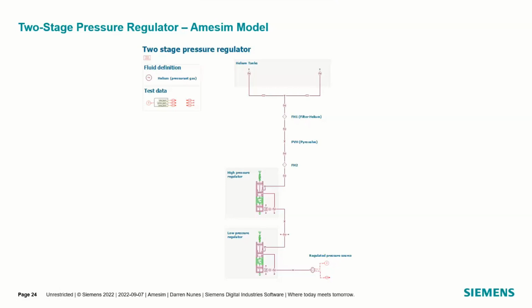The tanks are ideally insulated due to the lack of information. We really didn't look at heat exchange or materials involved. The two stages have the same architecture, and they're modeled using that component design like we saw in the past. They just have to counter the force of the spring. So for the high pressure chamber and the low pressure chamber, we had to discretize and change the different levels of spring damping, the sizing of the chamber, or the way the valve dynamics work.